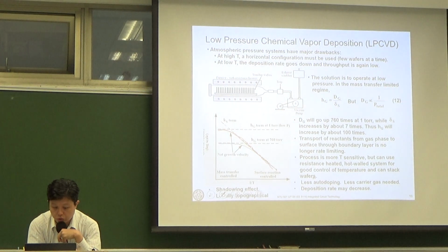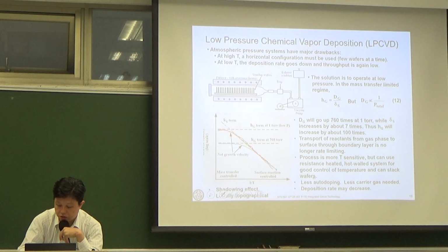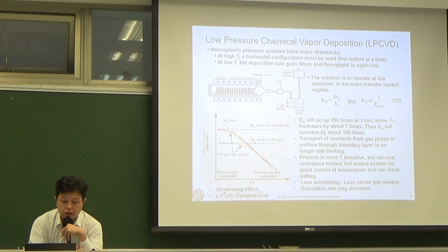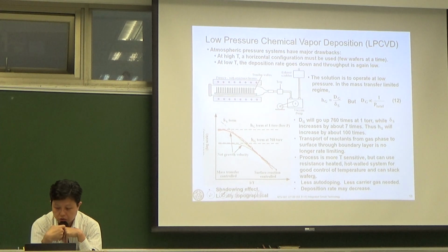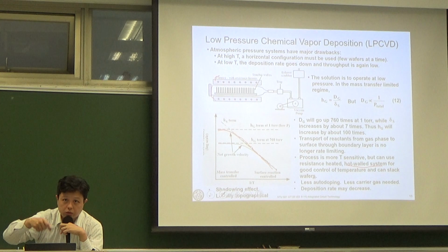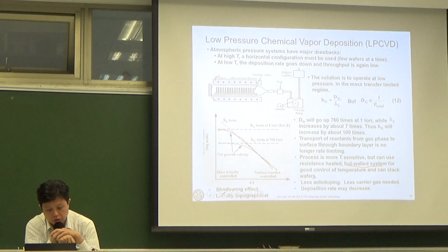We do not just use a bottom susceptor, those graphite susceptors with very good thermal conductivity, but right now we need a hot wall, which means the chamber is a hot wall system. You can see these four chambers now. You have to provide this good and uniform control of your temperatures.